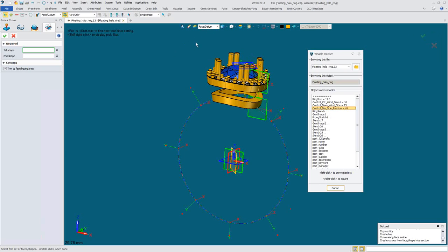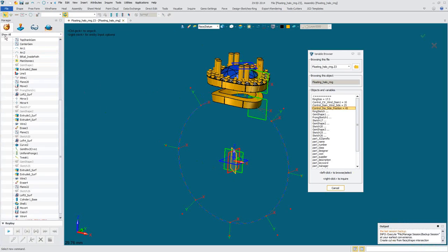If you pick them separately, that's okay. In other words, you can set this up to face and pick these two outside faces, activate the second shape, and then come in and pick datum. And you can pick the front and the copied one. You can work that way. Or you can come in and just set it to face datum. It's faster. Pick the two faces, come in here, and then pick these two datums. And approve it.